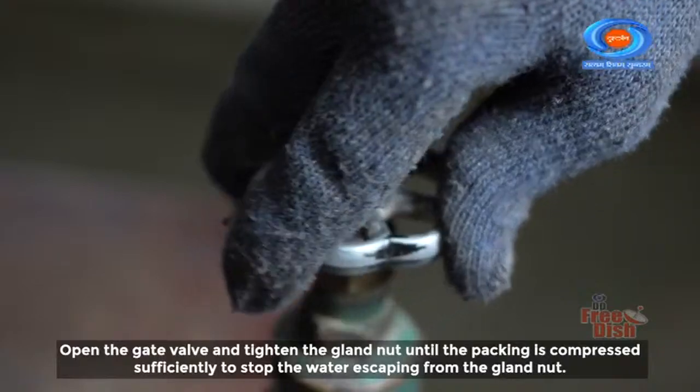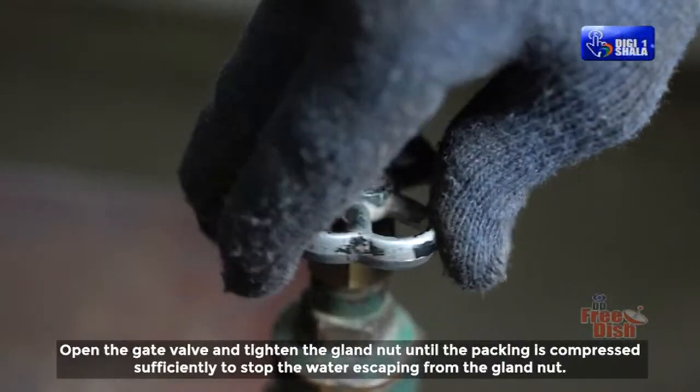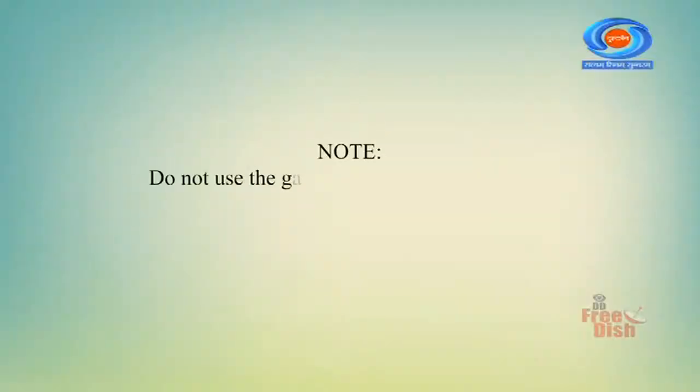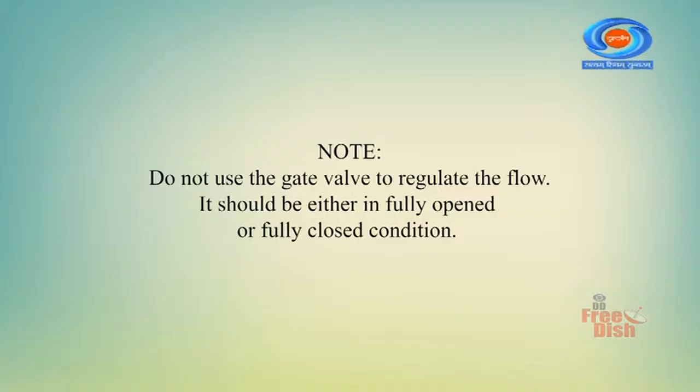Open the gate valve and tighten the gland nut until the packing is compressed sufficiently to stop the water escaping from the gland nut. Note: do not use the gate valve to regulate the flow. It should be either in fully opened or fully closed condition.